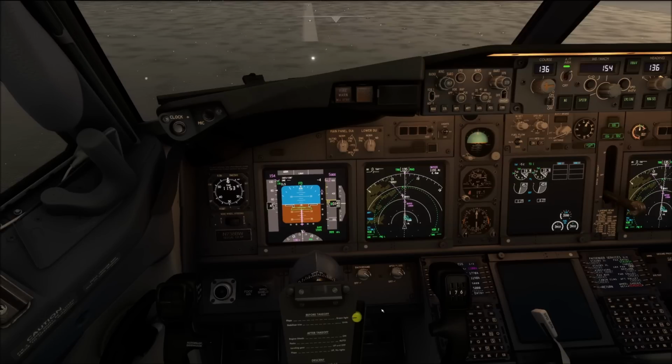And if the airport conditions and all the aircraft in the vicinity do not permit the engine thrust level to be increased to 70% N1, then set a thrust and timing consistent with the conditions. For example, when operating on a taxiway or runway where there are puddles of de-icing or anti-icing fluid, or when operating on slippery and contaminated surfaces. In many cases, it may be appropriate to line up when cleared and perform the engine run-up on the runway in conjunction with the takeoff.